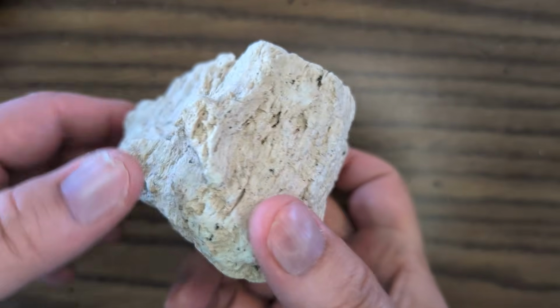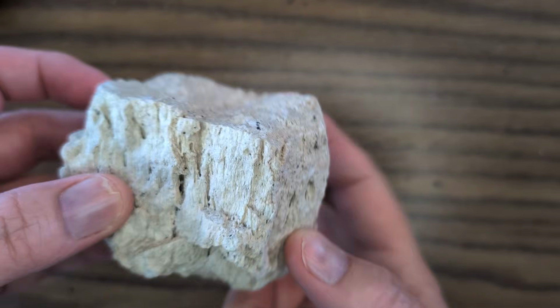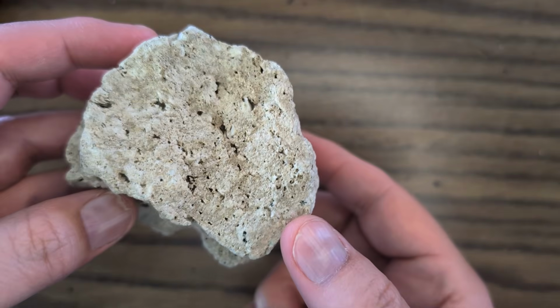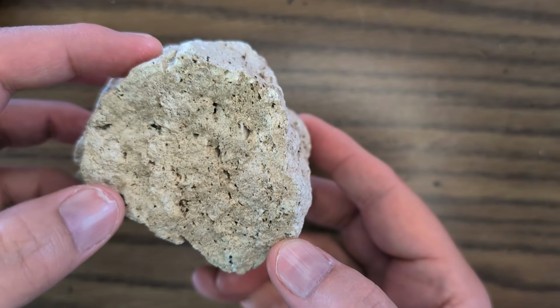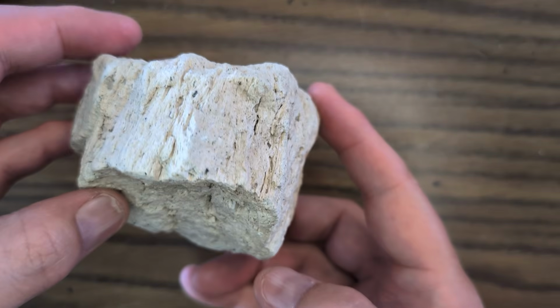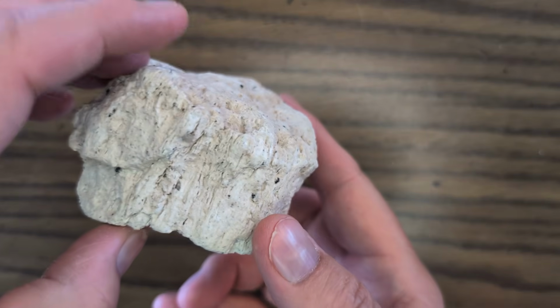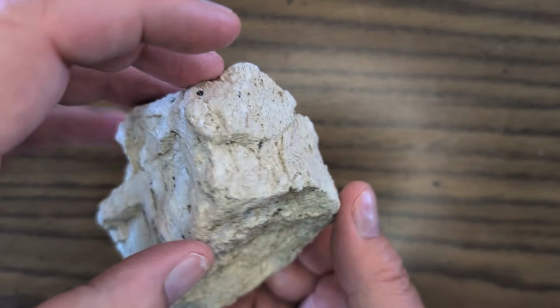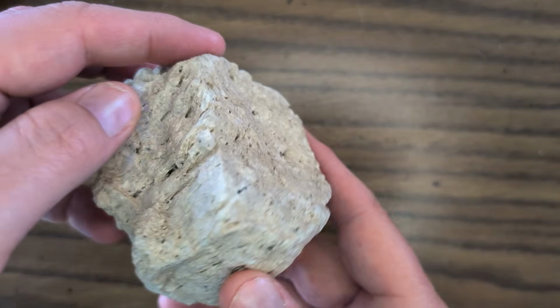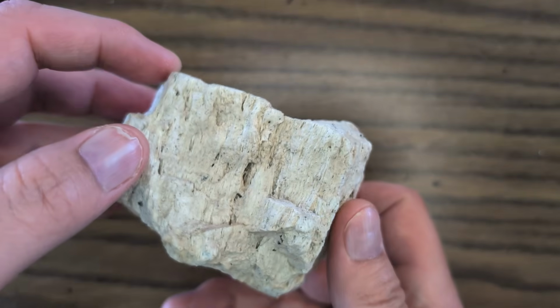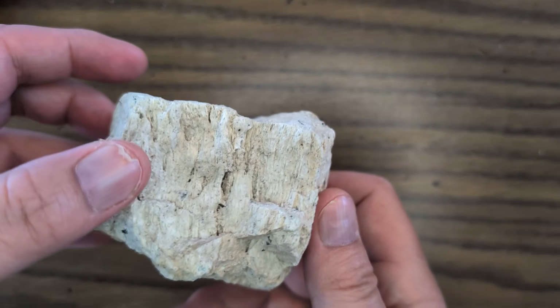Now, pumice has a very high porosity. In fact, it is up to 90% empty space inside. Now, that's a maximum value. Pieces like this are more typically 60 to 70% pore space, but that's still a lot of empty space in your rock. However, it has very low permeability. All of those tiny microscopic air pockets and the larger ones you see tend to be isolated from one another. And that results in it having very poor permeability, very poor hydraulic conductivity.